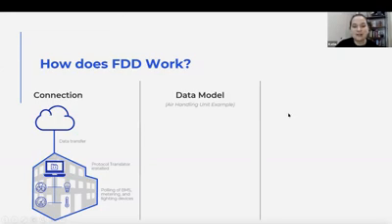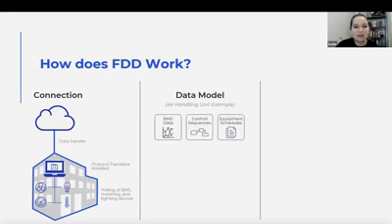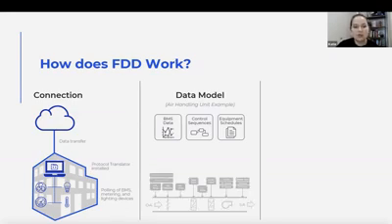So the next phase is the data model. We're going to use an air handler as an example. You're going to take your BMS data, your control sequences, and your equipment schedules, and I'll give you an example with an air handler of how that works. Right here below, you have a typical AHU. It's 100% outside air. It's got some dampers, some coils, some fans, some temperatures. So your FDD system will take that BMS data. It'll pull in your outdoor air temperatures and any of the data that it needs to make those conclusions.